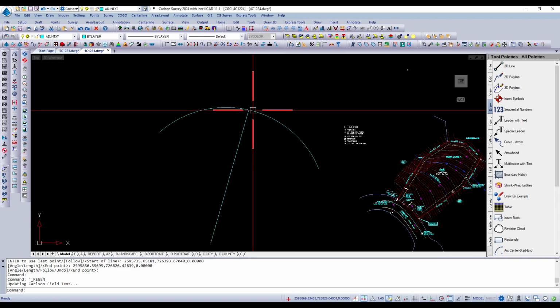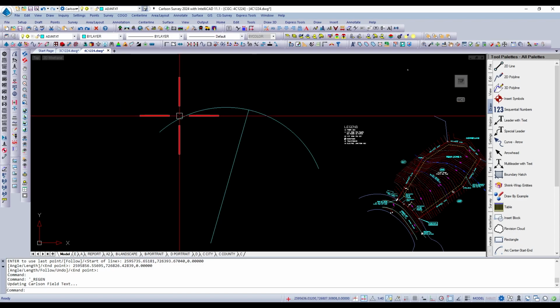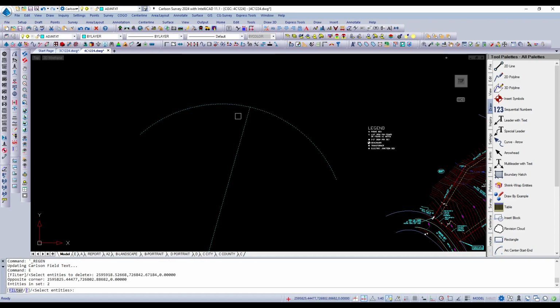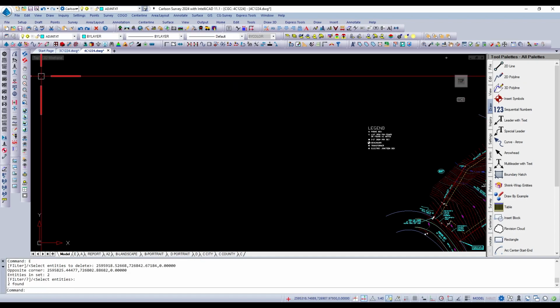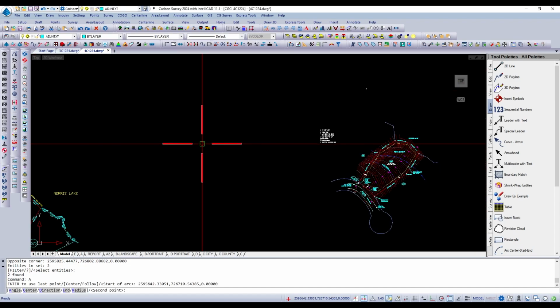It may look like one entity is not touching another, or that it's crossing or something like that, when in reality, if you hit regen, it's not doing that. It will display it correctly when you hit that. I like regen instead of redraw. Redraw doesn't...